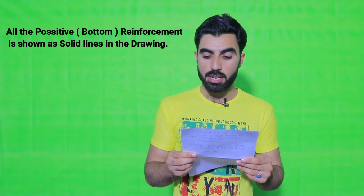So the first one is about main bars and distribution bars. As you know, we have two types of rebars in an RCC slab. One is the main bar, the second one is the distribution bar. All the positive bottom reinforcement means all the main bars in an RCC slab. As you know, main bars are placed at the bottom in an RCC slab. So all the positive bottom reinforcement bars are shown as solid lines in the drawing. It means main bars in an RCC drawing should be shown as solid lines, not as dash or dotted lines or hidden lines. It is useful for a site engineer, and also if you are working on a construction site. So you should remember that main bars should be shown as solid lines.